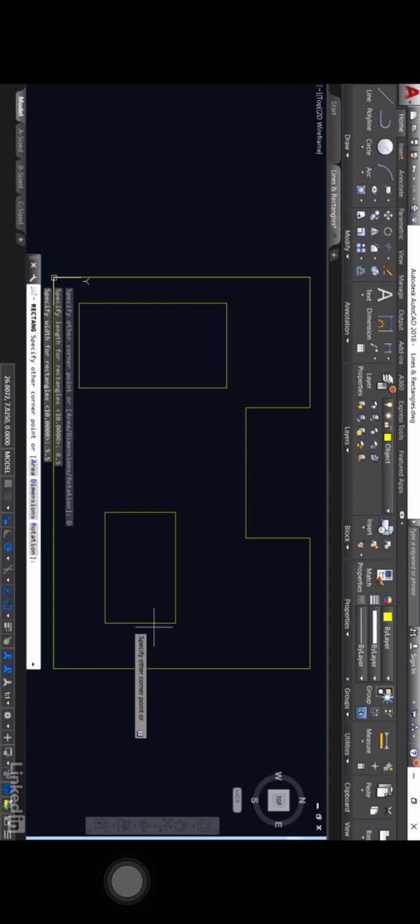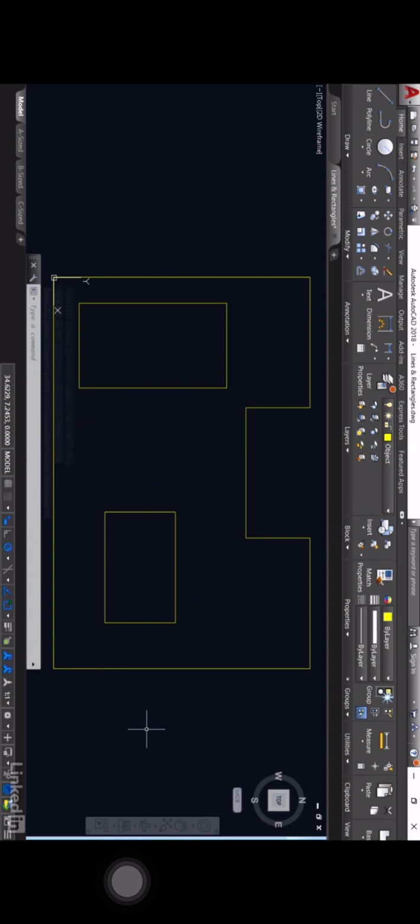Now, be aware that you haven't finished the command yet. I can now rotate that rectangle around the original start point, that original 18,4 coordinate. So I'm going to move it up, and basically I'm going for the top right quadrant. Can you see that as I go round? So top right quadrant, click once on the mouse, and it places your rectangle. So now what we've done is we've drawn some lines and some rectangles, and now we're ready to move on to the next video.